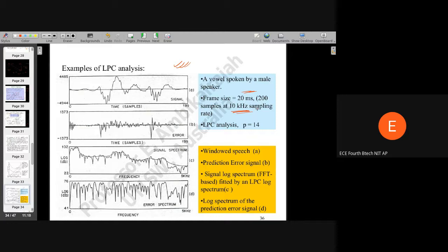So, from the speech signal, we obviously don't know beforehand the number of vocal tract resonators that are there. What is the true nature of the vocal tract system transfer function? We don't know. So we generally think that every 1 kilohertz there is a resonator. That means two poles. So we'll need a cascade of resonators. Here, let's say we assume 5 resonators. So 10 poles plus 4 poles.